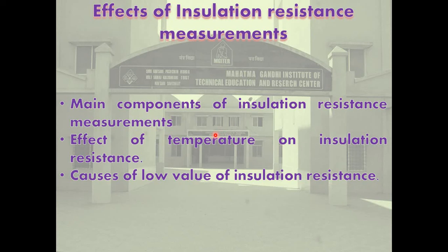Now, effect of temperature on insulation resistance. In case of a power transformer, what is the minimum permissible value of insulation resistance of transformer windings for 60 second reading? The insulation resistance depends upon the temperature. Therefore, when testing insulation, the temperature should also be measured.